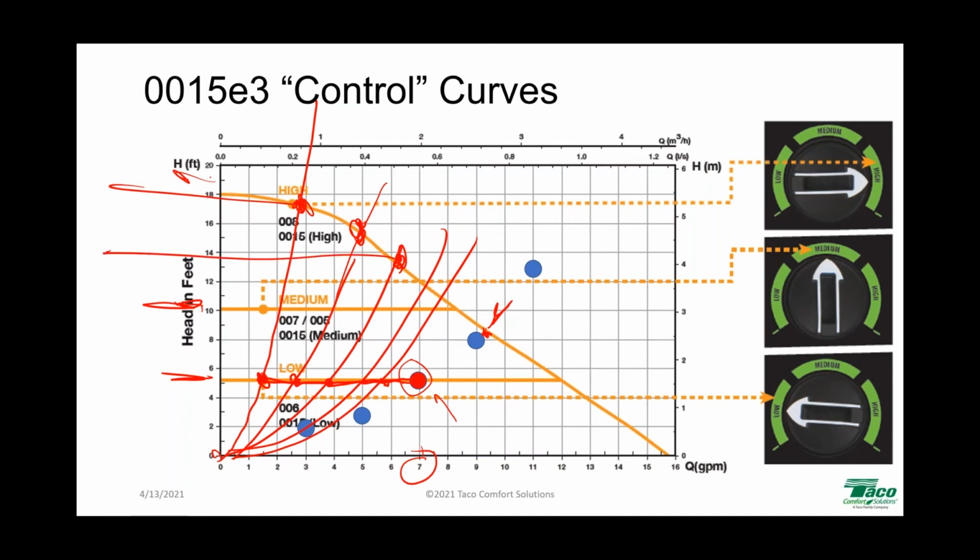If we're intersecting up here, that's where zone valves bang, when they're closing against such high head loss or high head pressure differential. If you've ever had zone valves banging, this is why. A lot of people say, hey, if you've got banging zone valves, put in a variable speed pump, that'll fix it. Yes, if you program it properly, that will fix it. If you don't, it won't. You're in charge of what happens. You're responsible for that pump the minute you take it out of the box. You're responsible for its operation. So this is stuff you definitely need to know.